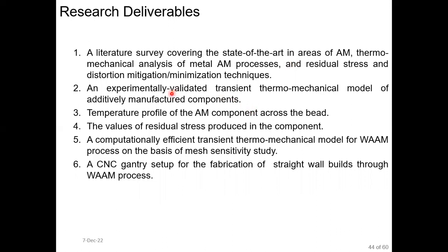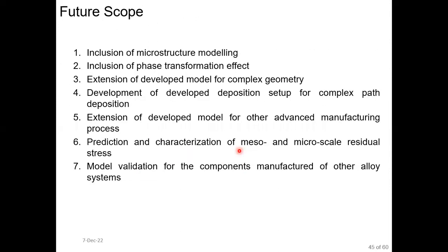After that, this study gives an experimentally validated transient thermomechanical model for additively manufactured components. Using that thermomechanical model, we can predict temperature profile and residual stress in a component of any length, width, and height. On the basis of mesh sensitivity, a computationally efficient transient thermomechanical model has been developed. And apart from that, a CNC gantry setup for the fabrication of straight wall builds through the WAAM process.